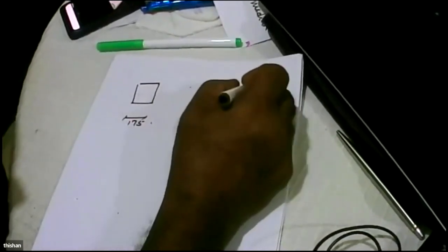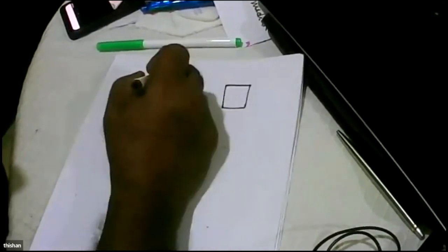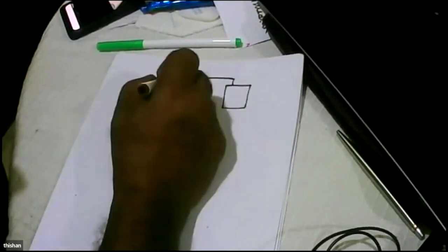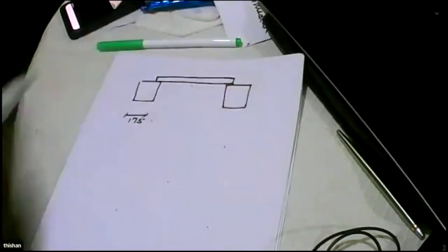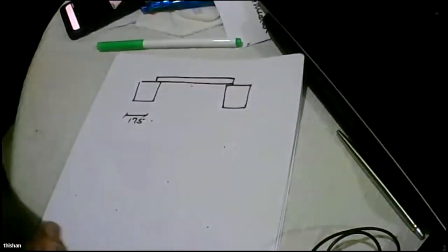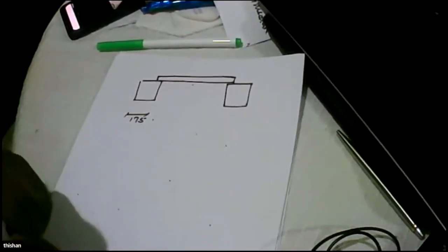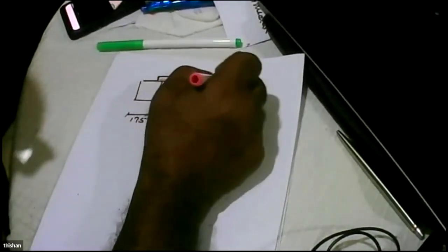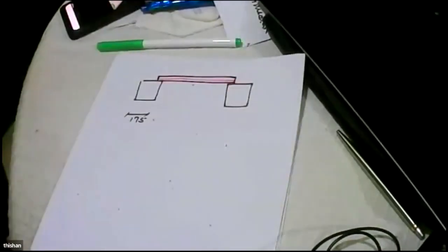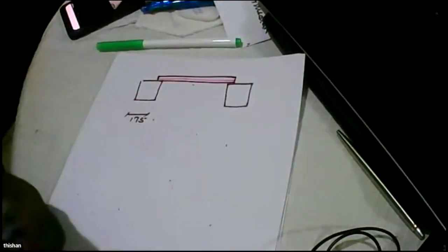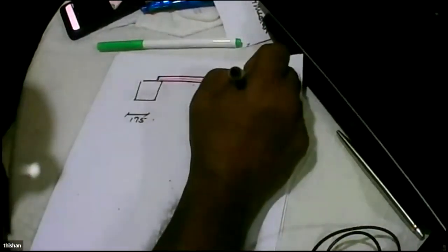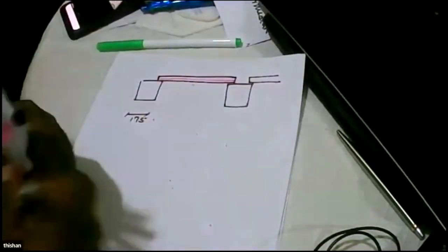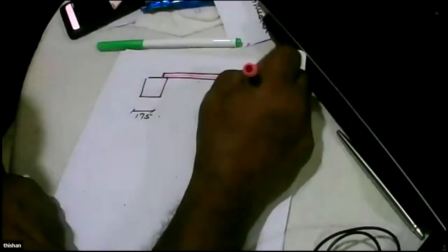And because these are small spans, a minimum bearing of 40 millimeters would be sufficient. But the important thing is, because we have only a small bearing, we make sure the reinforcement is of full length, continuing from here to here, because we don't have a cover problem, since we are going to put concrete here. So we continue the reinforcement to the very end of it.